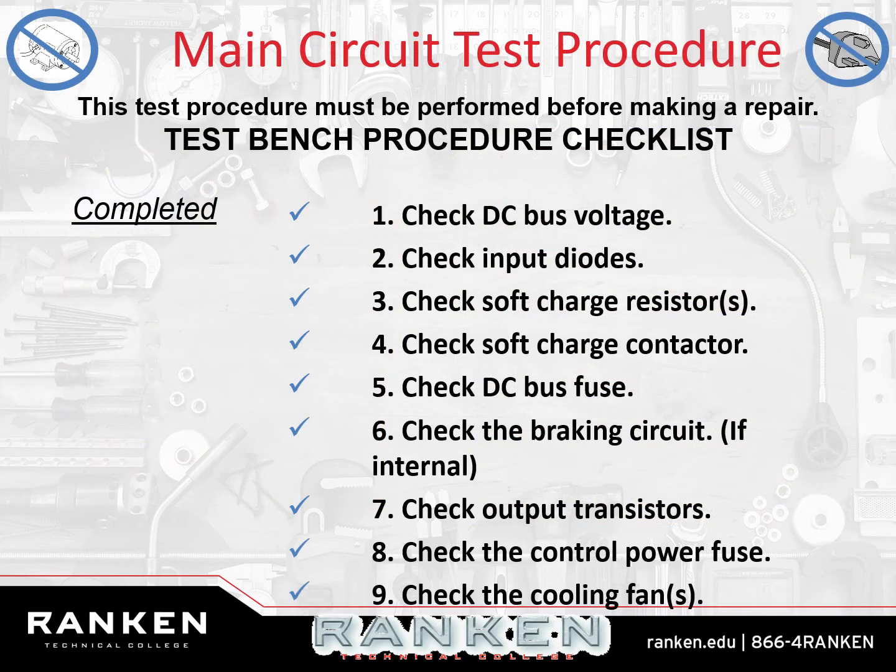So check the DC bus voltage. Like I said, that's going to be the big one. That's going to tell you if your drive is working pretty good. You know what's going on. You know you have voltage coming in. You know you have voltage going out. Check the input diodes if you have access to them.